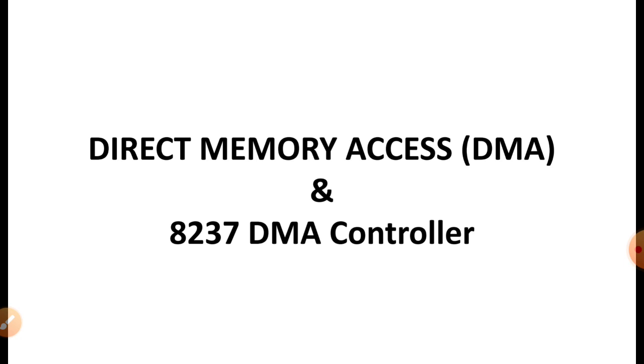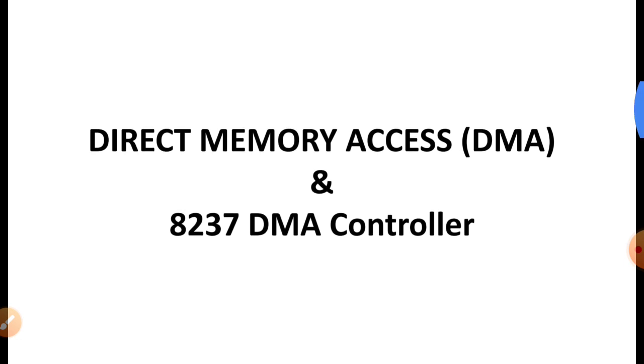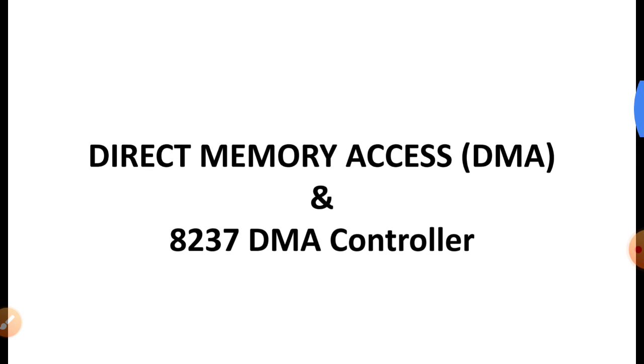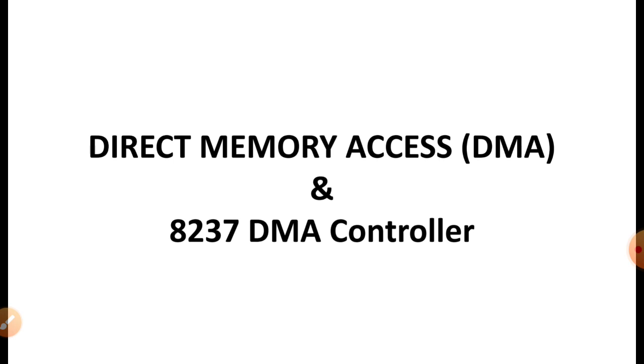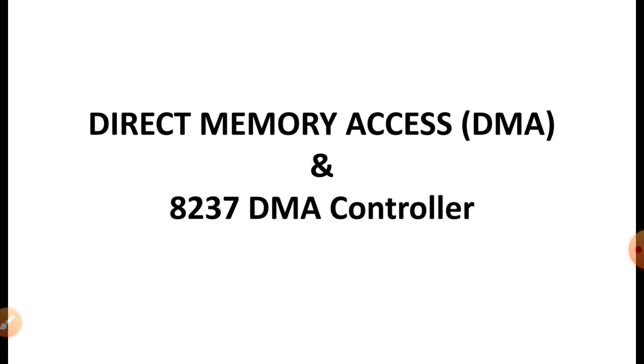So, if we have to transfer data from the peripheral to the memory, or from memory to the peripheral, or from one memory to another memory, then the normal process adopted is first to copy the data from the source to the processor, and then from the processor to the destination. Now, the source and destination may be the memory, or the peripheral, or one may be peripheral and then memory. So, it wastes too much time, because unnecessarily the data is being transferred from the source to the processor, and then from the processor to the destination place.